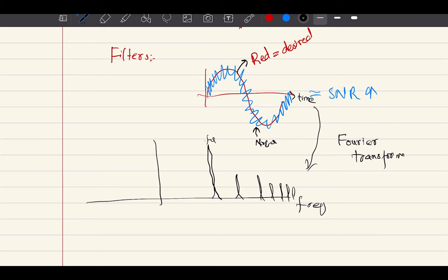So each will make some different frequency terms. These noise will have some different frequency terms, right? And then you will have this frequency. If you clearly observe this signal, your original, the red one, has a very low frequency. But the blue one is repeating very high, so it has high frequency, which means that all the noise in this case... it's not always true because it depends on the system and the transmitter, the receiver, and the noise factors. But just in our example here the noise term is caused by the high frequency.